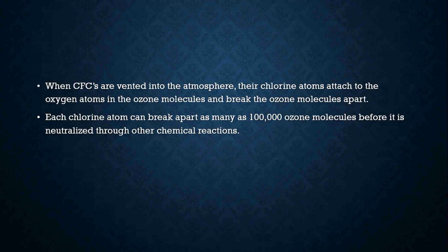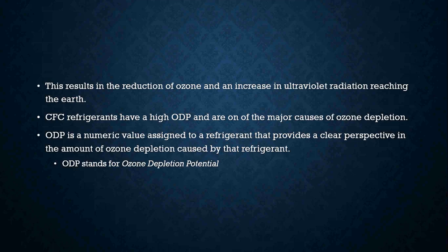This is also tied to greenhouse gases and ultraviolet radiation, because before we had to follow recovery techniques and reclaiming, we used to just open up the valves and let the refrigerant go. Can't do that anymore. We have to make sure that we recover all of the refrigerant into an external storage cylinder and then dispose of it properly.